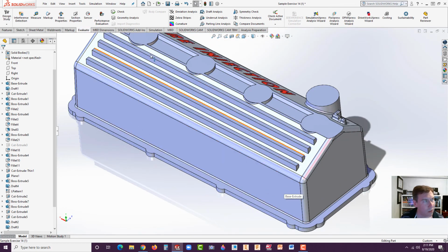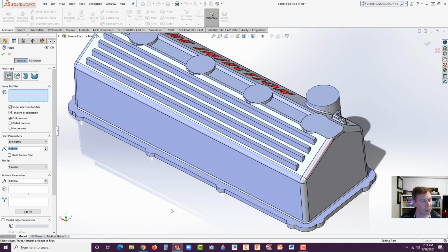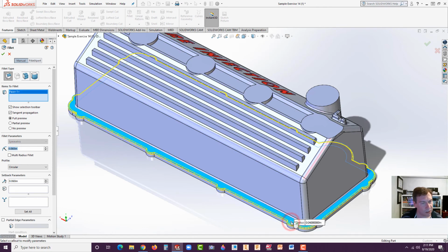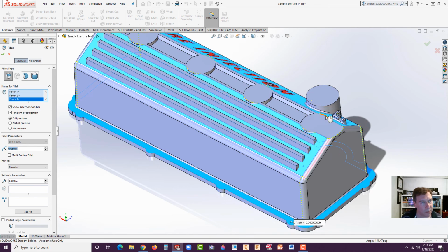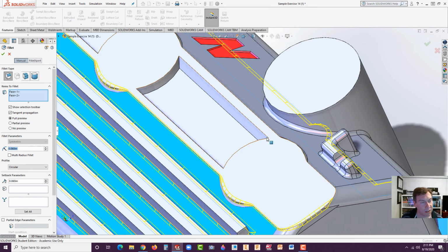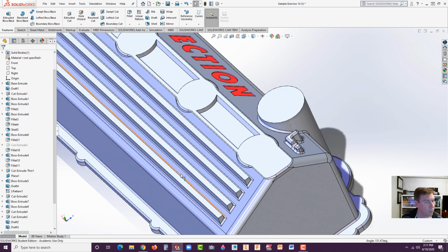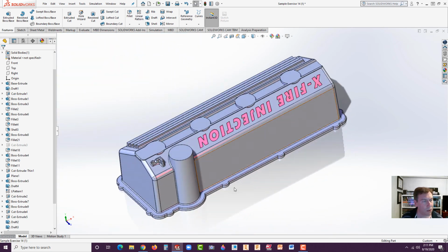Okay, and so as far as fillets go, make sure you just put fillets between 60 and 30 thousandths. So like I'm going to select this face here, I can select that face. This one will probably error it out. Sure enough, when you see that the fillet preview disappears, that means it didn't like that one. Okay, so let's try this edge here. Okay, that's good enough for this exercise.